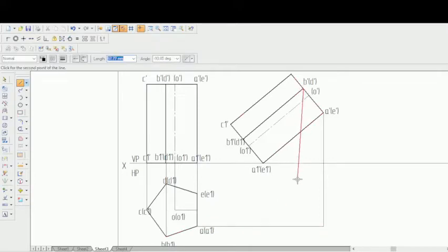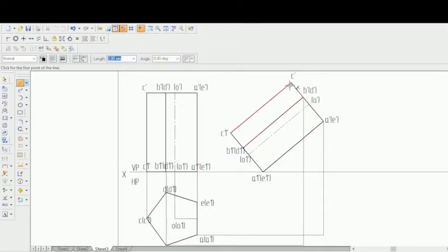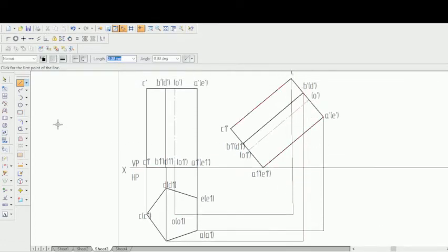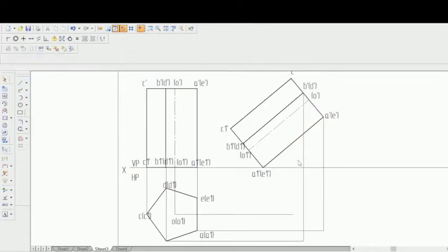Similarly from B dash, let me draw it here. See that the alignment indicator is switched on; if it's not, you can switch it on. And from C dash to here is drawn, and from D dash a vertical projector is already drawn. See that it is drawn correctly, and that the projection lines are straight.